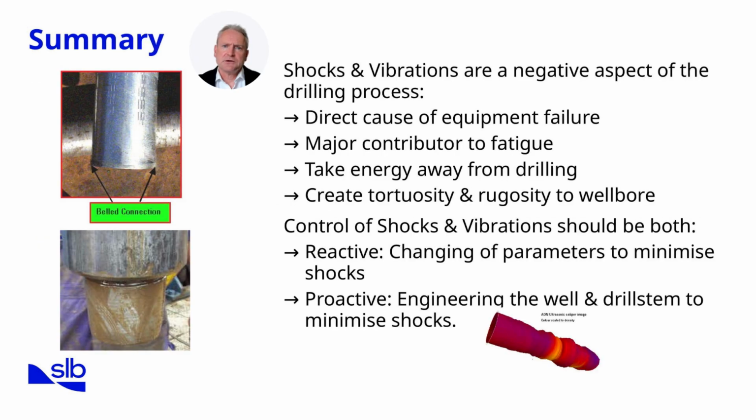To summarize, shocks and vibrations are universally negative in the drilling process. They directly cause equipment failure by overstressing drill string components and accelerating fatigue. They also consume energy that would otherwise go into rock cutting, which reduces efficiency and increases costs. Another consequence is the effect on well bore quality. Excessive vibration leads to tortuosity and rugosity, making the well bore harder to drill and more challenging to complete. This creates long-term implications for casing running, cementing, and production.